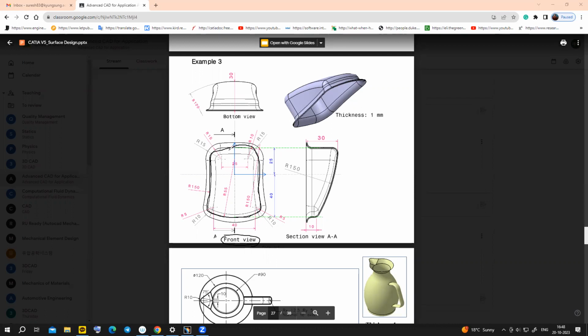After making the bottom sketch, we extrude that one by 30 millimeter. At least by 30 millimeter. You can extrude more than 30 millimeter, later we can trim, right? After finishing the extrude surface, we have to make the top surface using sweep surface. Okay, sweep.